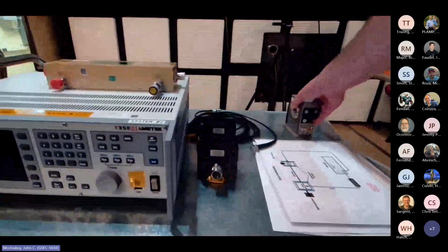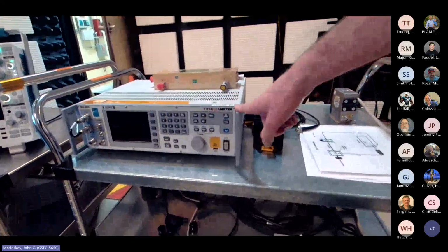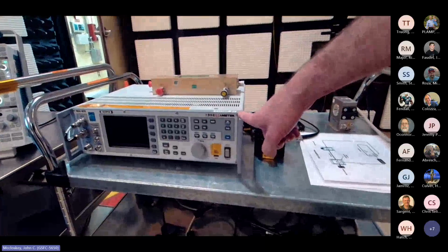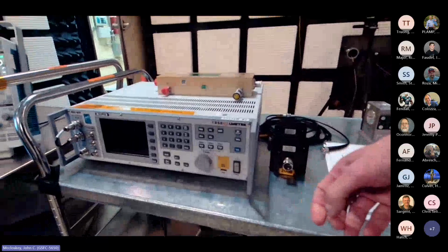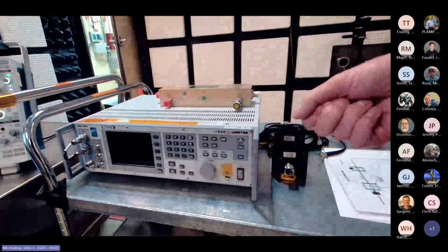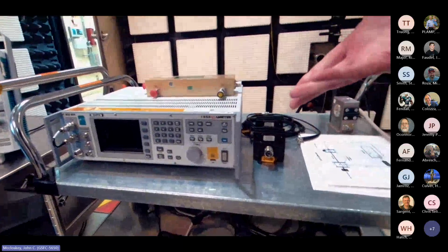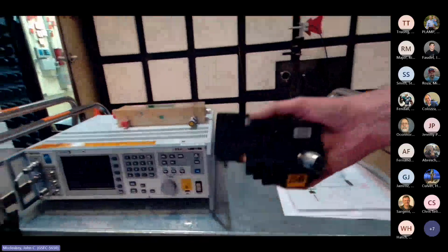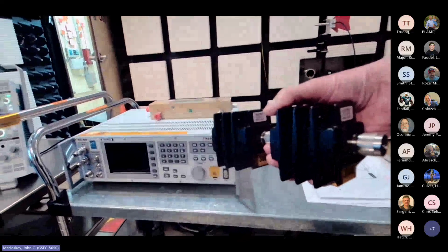Oh, and by the way, when you do use an amplifier, whatever power the amplifier is, I don't remember what this is offhand, but I think it might be up to about 500 watts. That's a lot of amplifier power. So if you don't need 500 watts for your actual signal injection, you don't want to rely on software control to limit the power you can inject into your equipment under test. If you inject 500 watts, you can damage stuff, and we don't really want to do that. So you usually are putting a hefty amount of attenuation on the output of an amplifier with that kind of drive capacity.